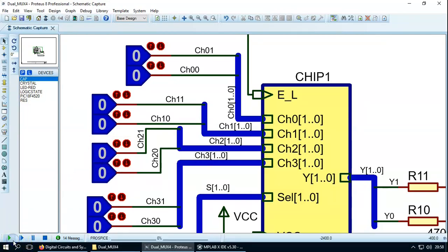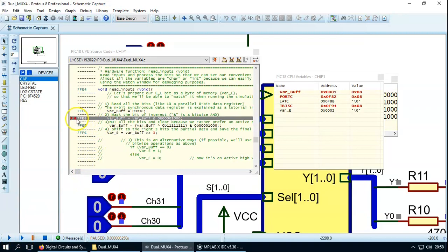So if you run now, you are stopped again at the same breakpoint. Now if you run continuously, look at this. Now 7.5 microseconds has elapsed, exactly 1/4 of the time required before, because the frequency of the clock is 4 times faster. So everything looks fine here. This is the kind of environment that you have to organize on your own, so that now, if you like, you can make modifications, changing the masks, adding new bits, because you have it all, okay?